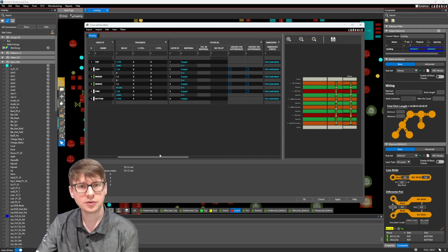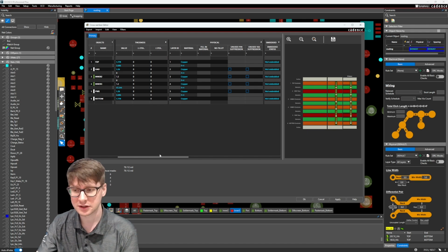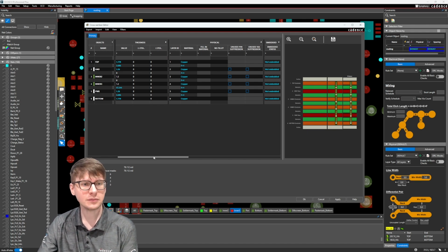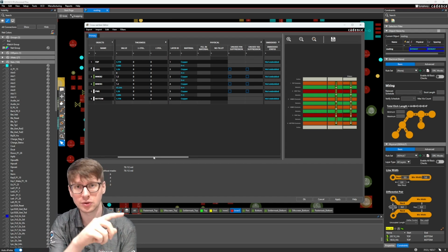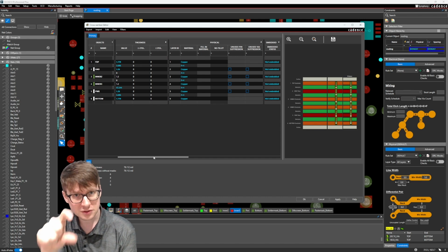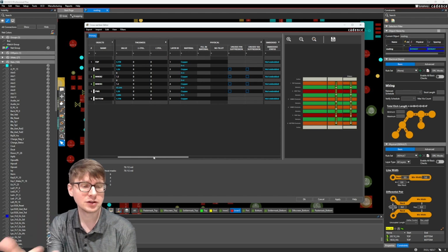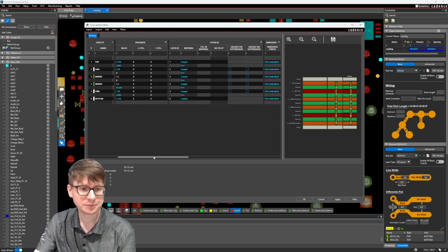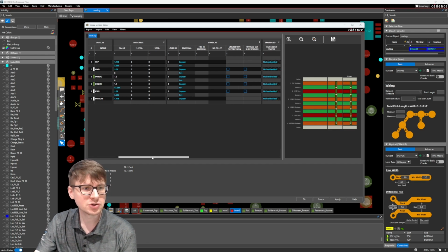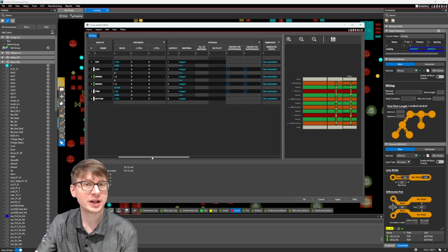And also, if you're doing some high-speed routing and are trying to match the signal lengths for propagation delay, and you're including something like the Z-axis delay, for example, if your signal goes from the top layer through a via to the bottom layer, how thick those layers are will impact your total etch length. So making sure that this is correct is important and usually can just be directly copied from whatever stackup is provided by your manufacturer.